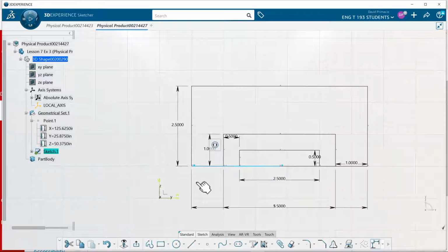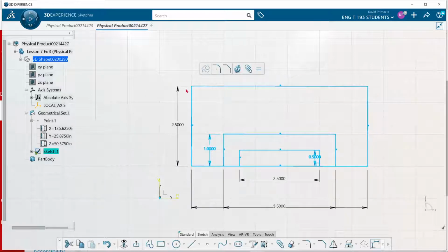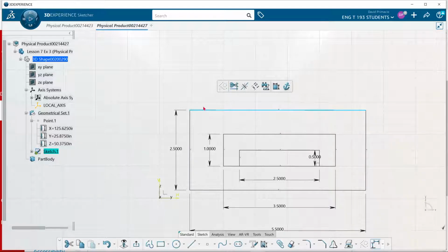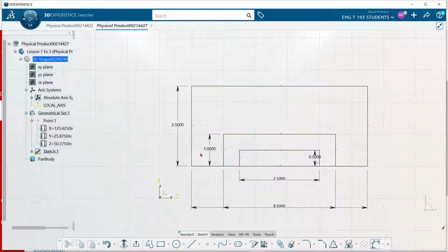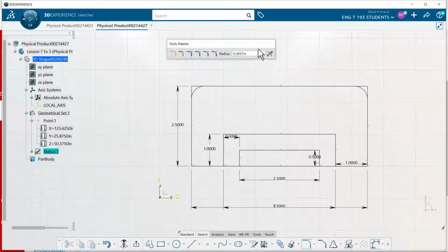So when I move this rectangle, the whole thing should move. If I undo the auto constrain and I move this rectangle, the other ones don't know to follow. So to lock them all in position, I'm going to highlight those, auto constrain it, and let it find the geometrical constraints to link all 3 lines to this bottom line here. I'm going to highlight this top and do the corner because I want to keep those the same. And that radius value is 75.